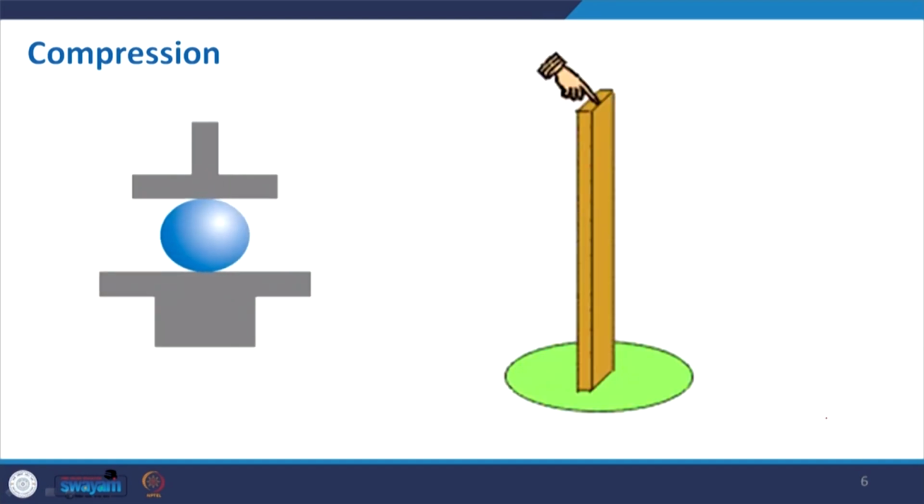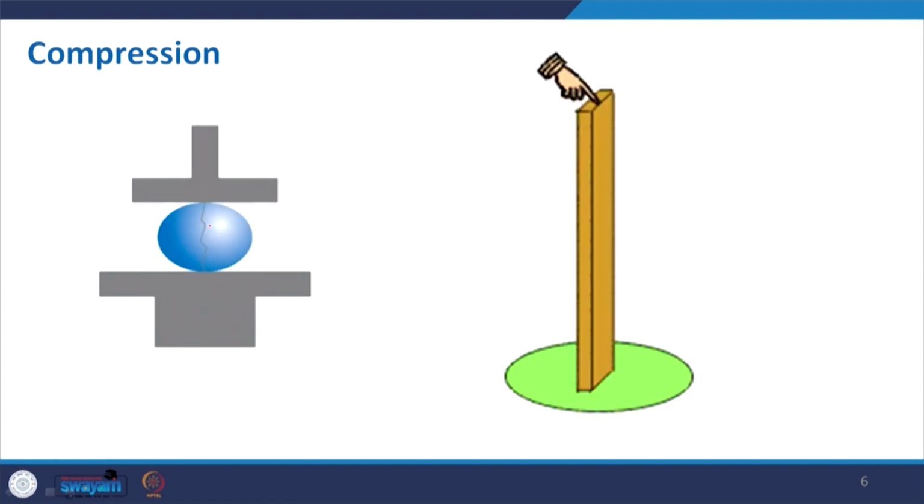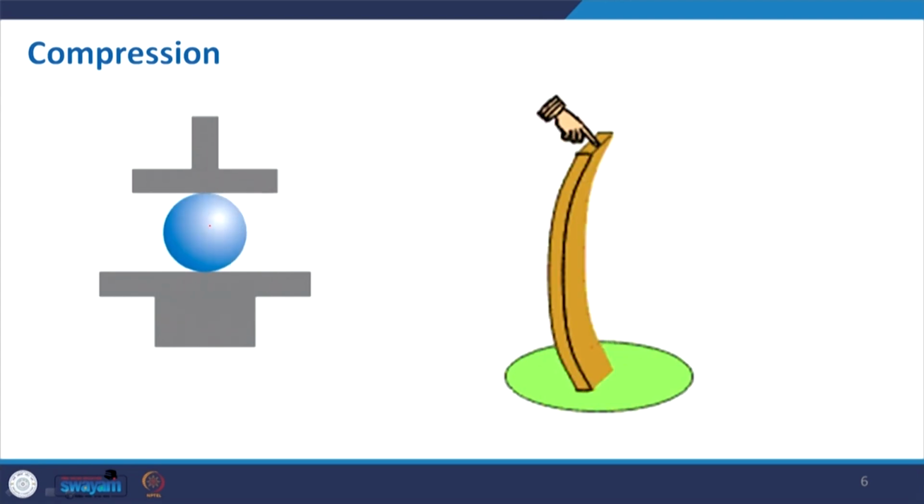Here we have images. They show what we said: in a compressive stress, how cracks develop. After compression it will go to the ultimate stress that it can hold, and then after that it will break. But in the other case, this is an example of a long column, with quite a lot more length compared to the cross section, and on applying load it will have buckling. So, in this it is buckling, here it is crushing.